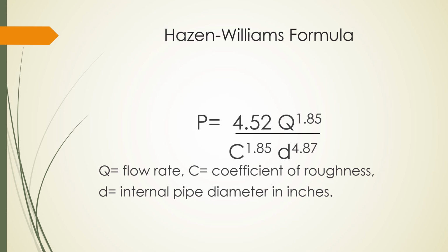And a diameter of 6 inches to the 5th power is 7,776, roughly 25 times more than a 2-inch line. And since that's in the denominator, it makes the overall friction loss less. So we need to be cognizant that the larger diameter pipe will result in overall lower friction losses.